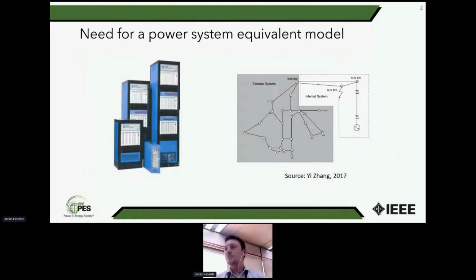First, the protection functions evaluated were related to power system dynamic phenomena, so it's crucial to represent the dynamical phenomena with high accuracy once we are going to test them. Second, the hardware-in-the-loop testing equipment that we have presents a limitation of the number of elements that can be represented, usually tens of elements.